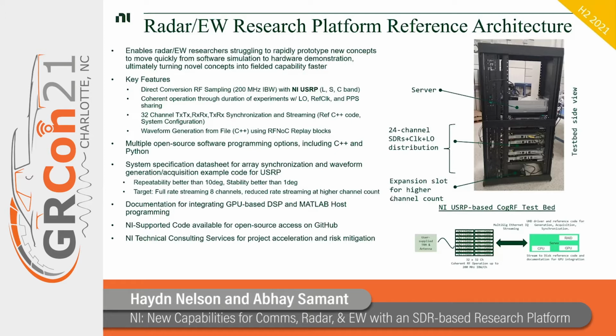The open source software is built in C++, and it will be available on the Ettus GitHub page. For the 32 channel system that we have put together in the lab, we also provide the system specifications for how the phase difference between the multiple channels is repeatable from run to run with a session reset, and also as we change configurations such as power level and frequency level.